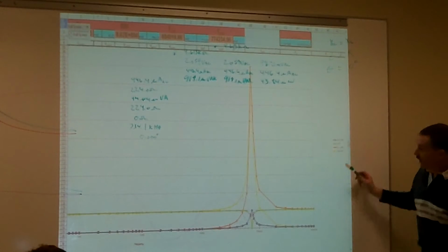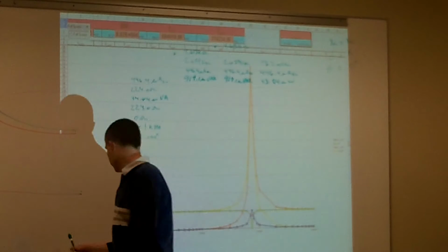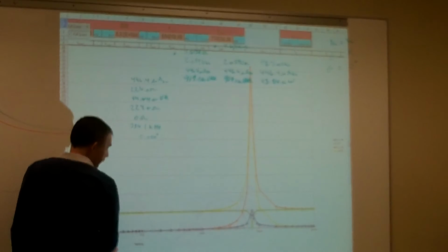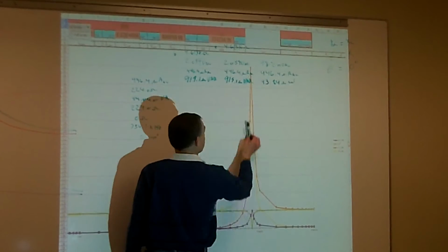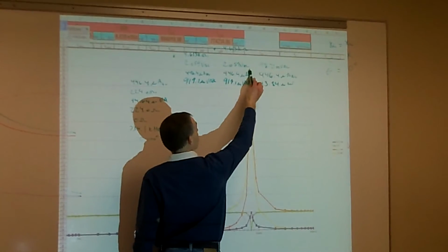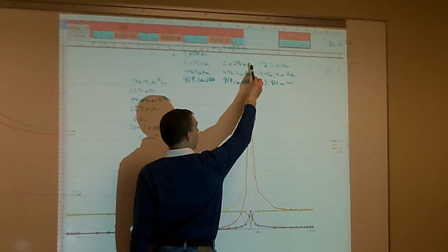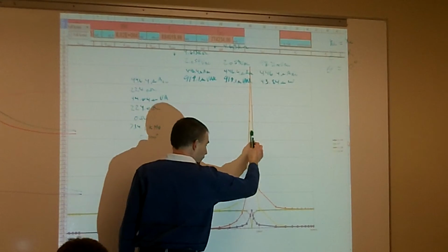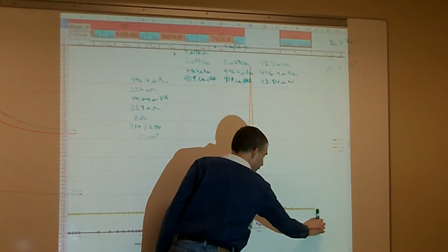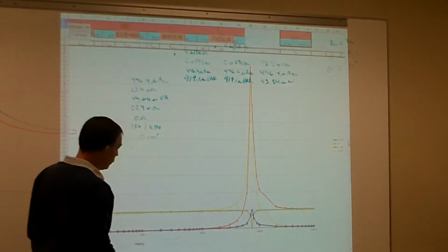My voltage of my inductor, which is orange, starts out very low, starts to go up, and then when I hit my resonating frequency, you can see all of a sudden this thing starts to react. It shoots up to that 2.059 volts AC, and then as I keep on increasing my frequency, it's going to drop down and then drop to the source voltage.